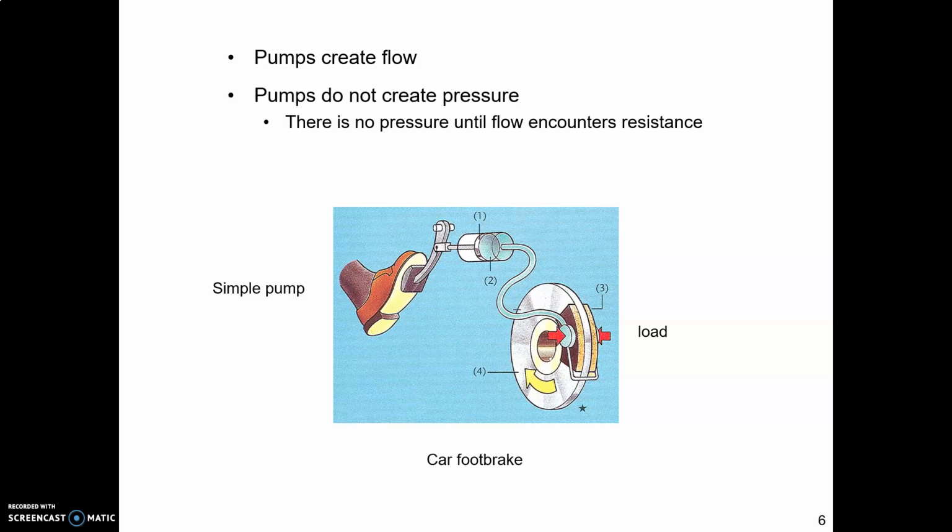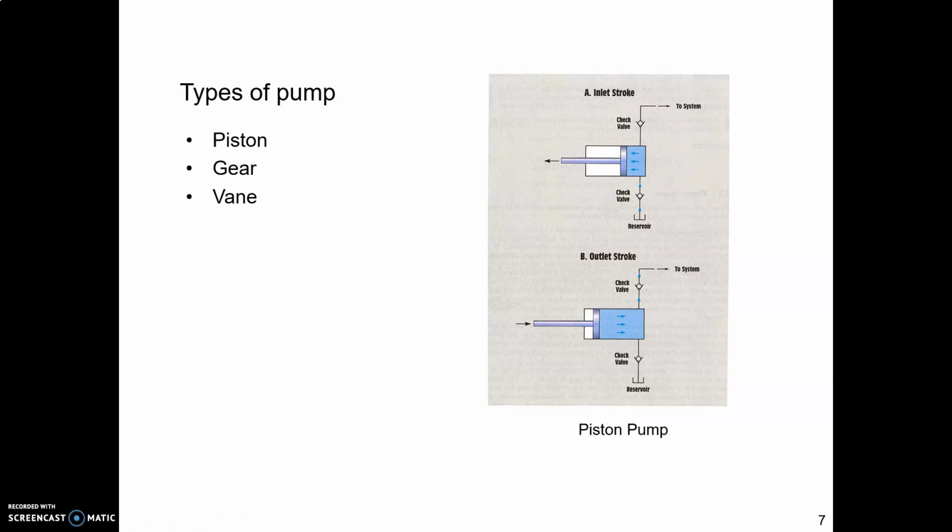Another point of clarification, pumps by themselves do not create pressure in the system. What they do is they create flow. If you had a pump pumping away and you had an open hose at the end, well, there would be no pressure other than atmospheric. So it's when the fluid encounters a load, that's when the flowing fluid creates pressure.